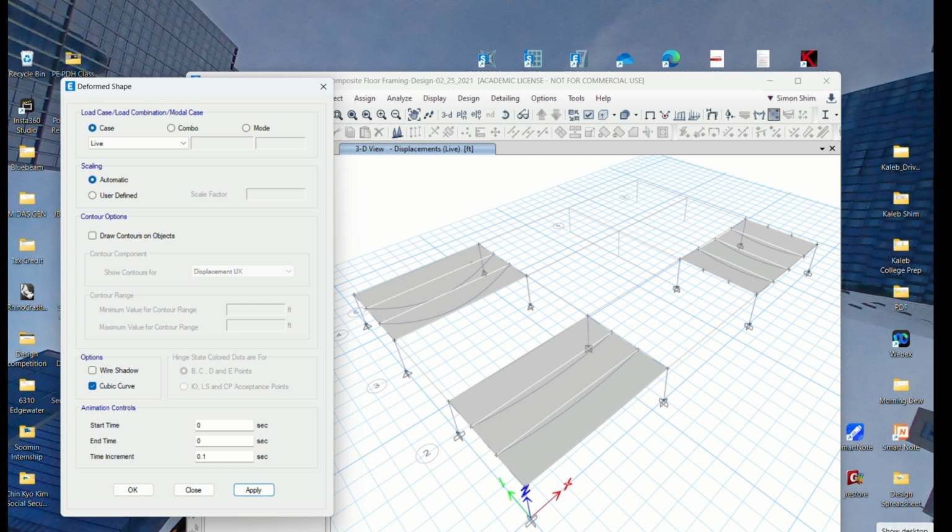Beam and slab are not connected, so they use basic moment distribution. We calculate the equivalent line load for, let's say, live load, whatever the live load in PSF, area load times tributary width. Those line loads are used, and they show the deflection diagram and numbers in this mode, which means they don't recognize any composite action here.